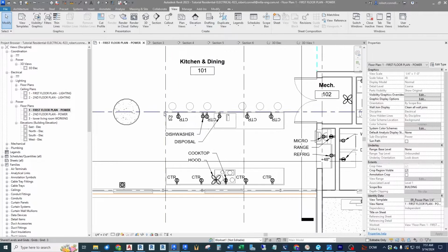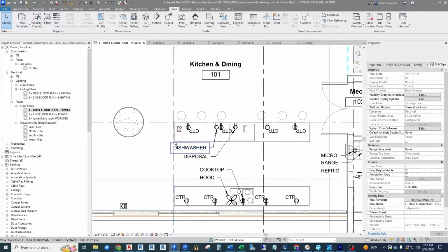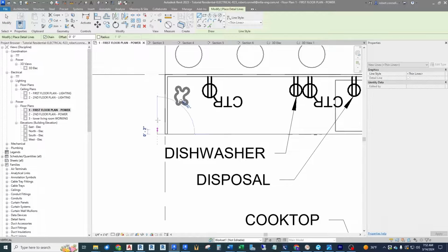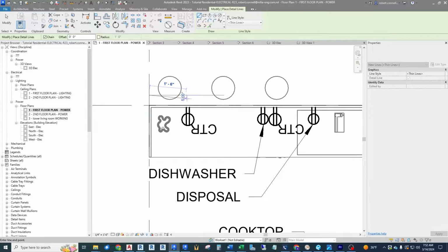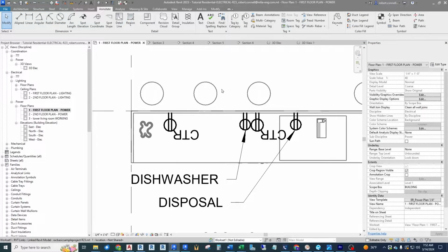And what I realize is that the back of this counter is actually going to be considered a wall space within here. So we are going to need to treat that just like a wall. So we need to be 6 feet from the end of this, wrap around the corner. So we can include the corner as part of the 6 feet. So we have a distance of just over 2 feet. So if we're within 3.5 feet from here, we should be good. So I'm going to put one right in front of this. This is just a stool that can be moved around.